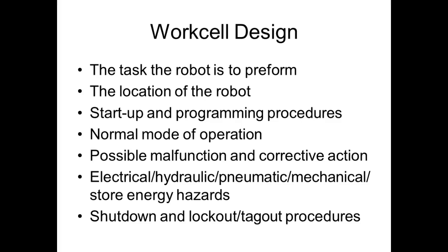So just about every one of these systems has that ability, right? Shut down and lockout tagout. So lockout tagout is a method. In the industry, basically every power source is supposed to have a method of locking out the power. So we actually put a lock on there. These have to be key locks, by the way. They can't be combination locks. How many keys are there? Usually there's one. That belongs to the owner of the lock.